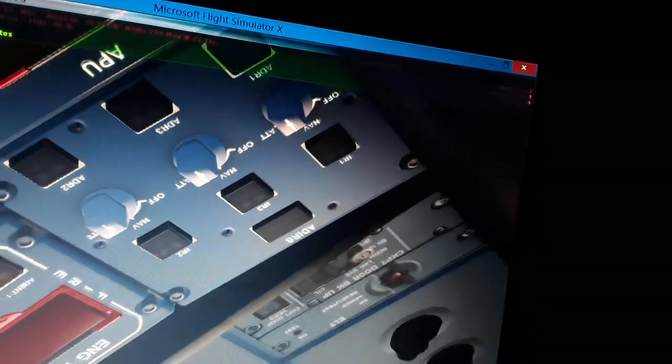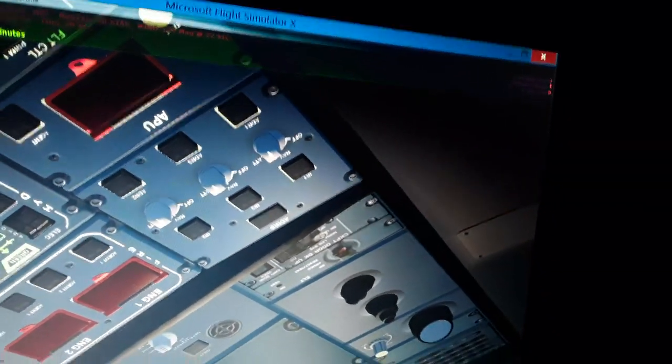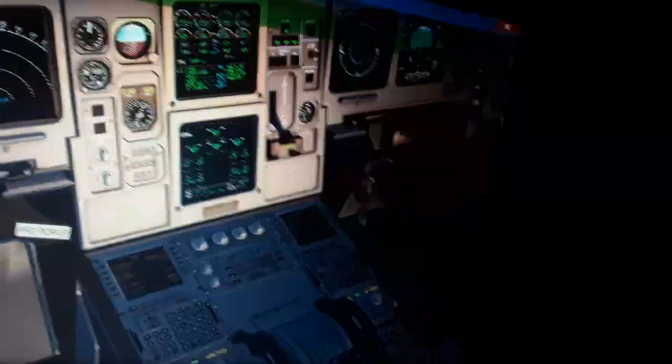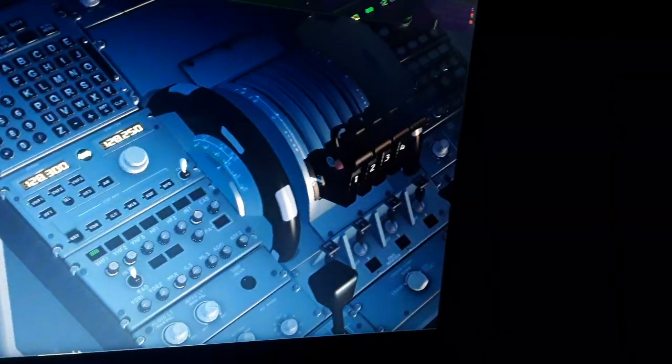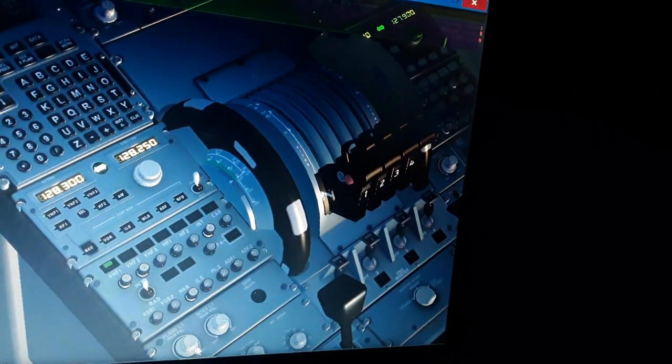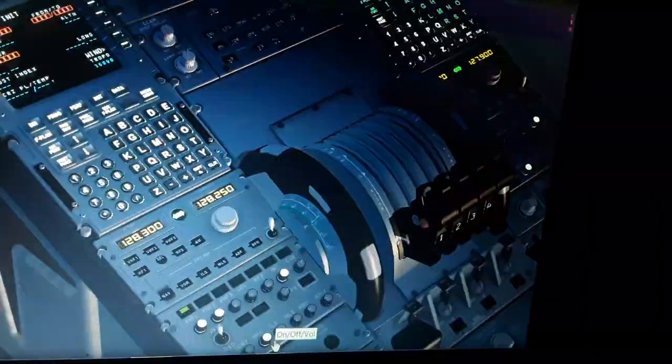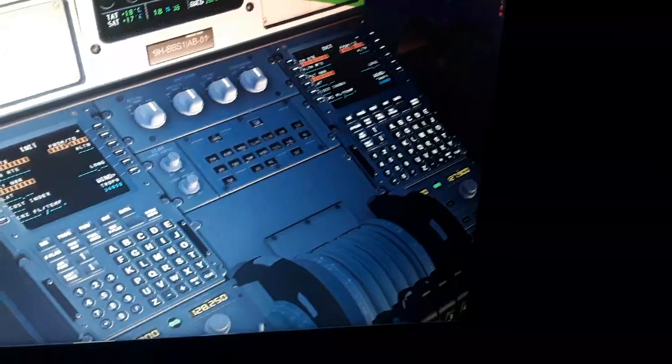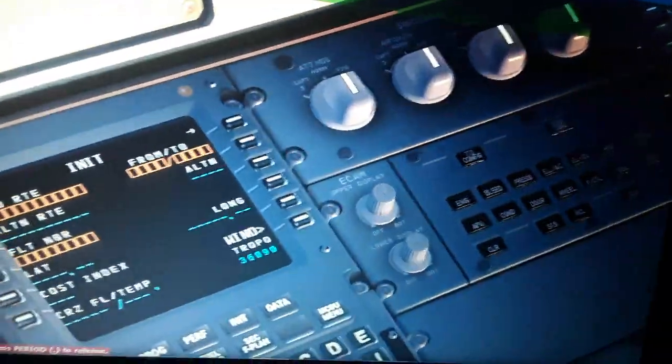It displays magnetic or true heading, GPS position and gyroscopic acceleration, which makes a hybrid display over here. It's also fed by the flight management computer, which manages the aircraft in flight from takeoff to landing, completing a complete flight plan. Here you can see the CDU.